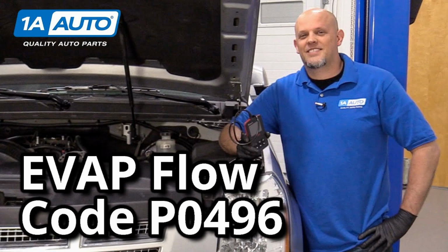Disconnect the cable connected to the fuel tank pressure sensor. Remove the old fuel tank pressure sensor. Replace it with your new fuel tank pressure sensor. Reattach the cable to the fuel tank pressure sensor. Lower the rear seat and carpet once you've finished. Test drive your vehicle.